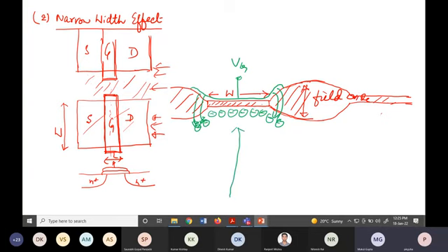So if you plot VTH over W, it remains constant. After that, as W increases, the VTH is going to increase. Now the way this was managed later on is not using field oxide between adjacent devices, but you can have something like trench isolation.